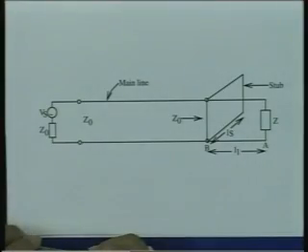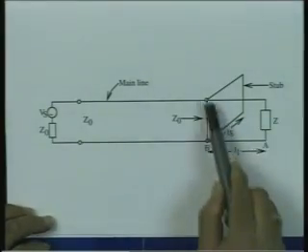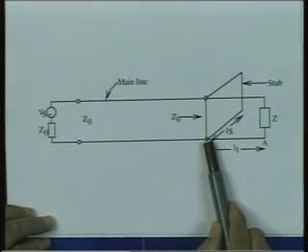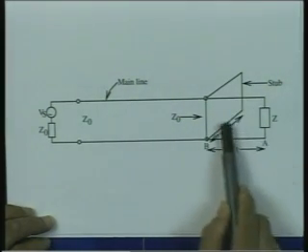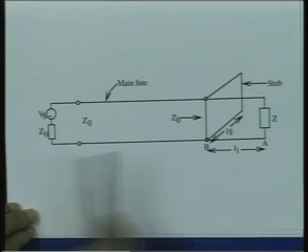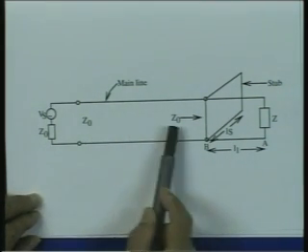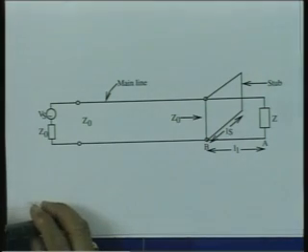When the two reflected waves reach this point, if we make sure that these two waves are equal in amplitude and opposite in phase, they will cancel each other at this location. So, the reflected wave coming from the stub and coming from the load, if they can cancel each other, there is no net reflection beyond this point, or in other words, if there is no reflection at this point, on this part of the line the impedance is always equal to the characteristic impedance.